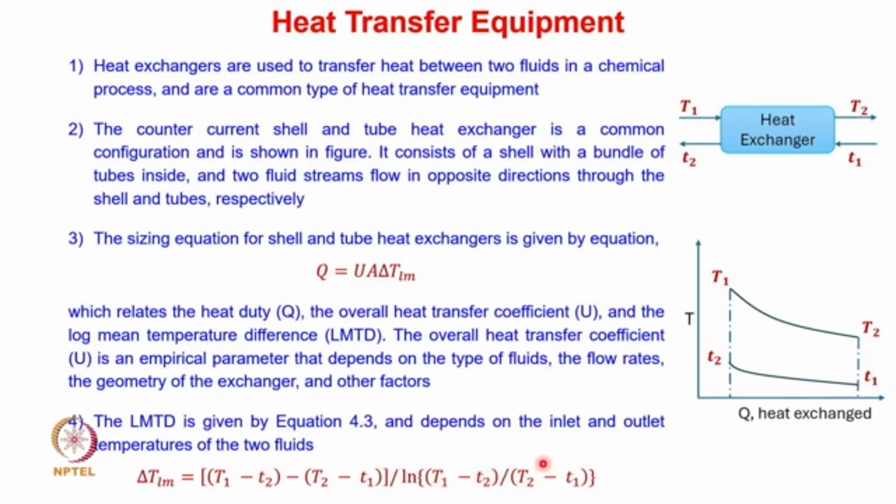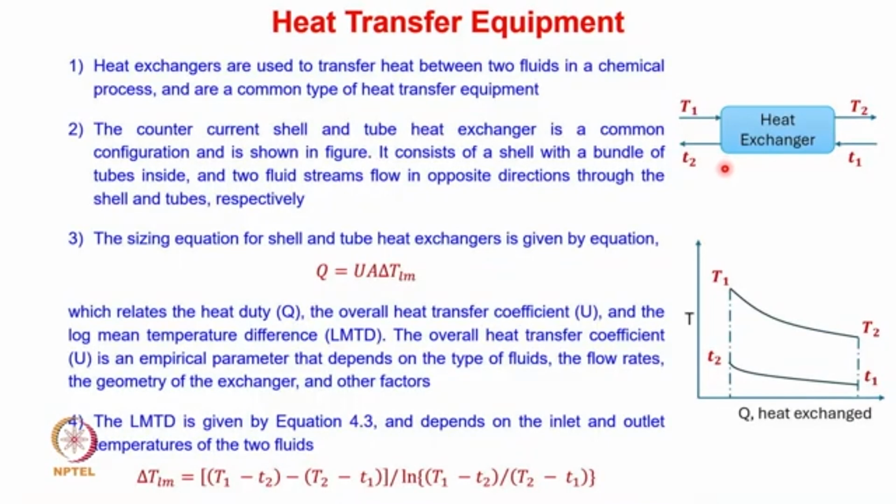You can see that the log mean temperature difference is primarily used because this temperature difference is varying as we move from one end to the other end of the heat exchanger. So to accommodate this variation in temperature, the log mean temperature difference is used.